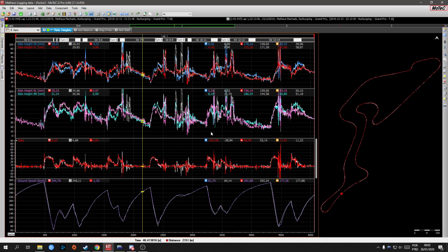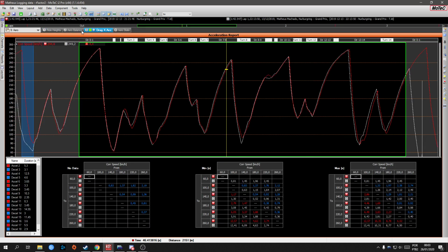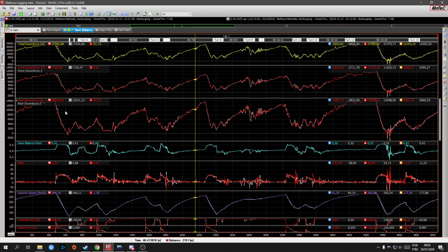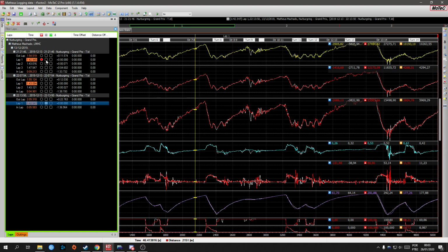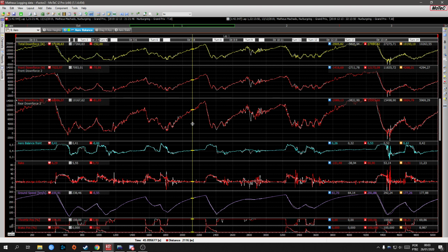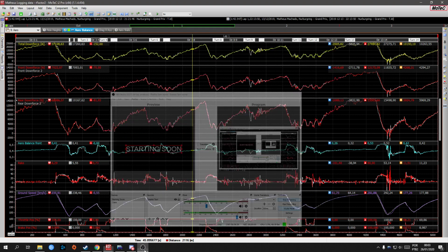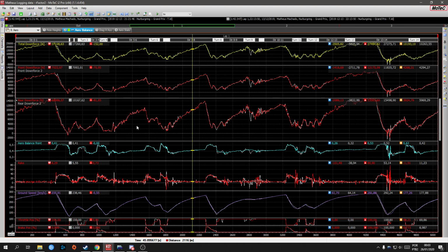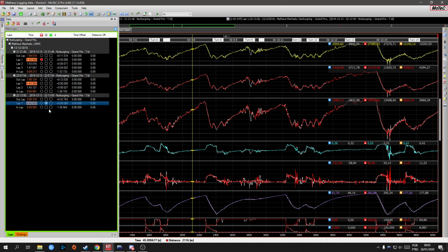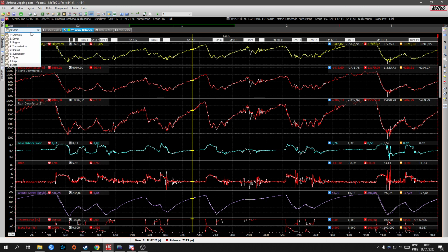So here, what I did is I increased the overall downforce level of the car, having less rear wing, and the aero balance compared to the start was about the same. So I noticed that I needed more downforce at the front, so probably the car was a little bit oversteery, but I saw an indication that it was getting better over time. So that's what I wanted to do, find a compromise, and you can see the lap time improved by a little bit. So yeah, that's how I usually analyze this.